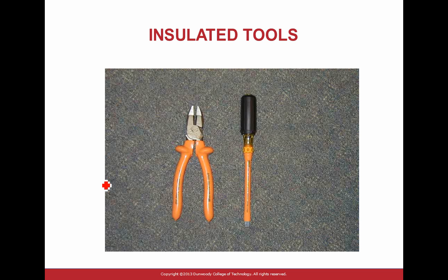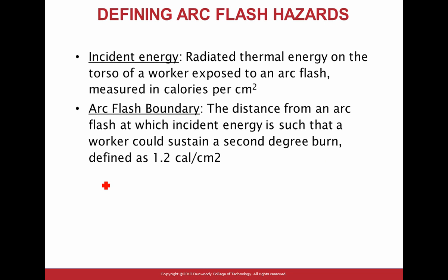So yeah, with the gloves, and remember, these are just for shock. These are supposed to protect you from shock. Remember the arc flash. The arc flash will require you to have this and the suit and whatever else is needed. Okay, defining arc flash hazard. Now this is the shock. Any questions, guys, about the shock before we move into the arc? The shock is easy. All you have to do is grab these two together when you're working energized and grab insulated tools, and you're good to go. That's for a shock. Don't touch anything with your elbow. So if you grab these two, you're protected from the shock.